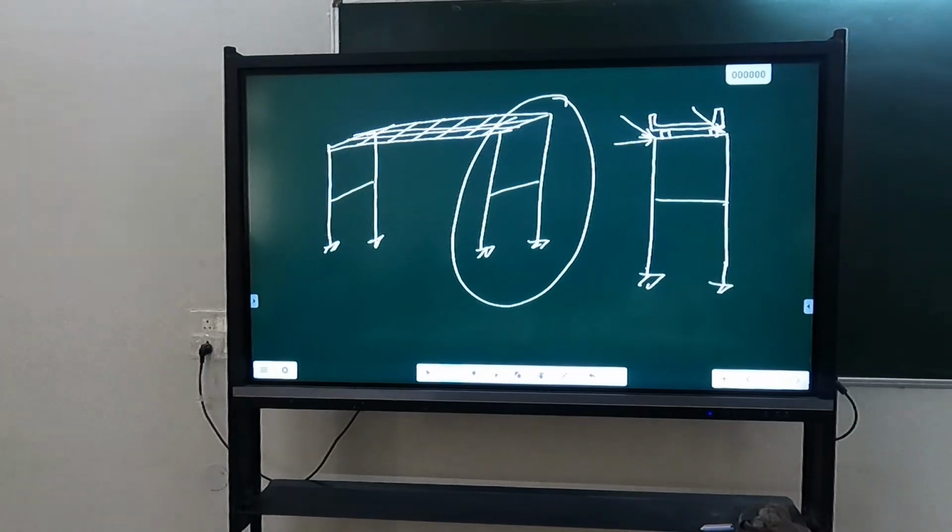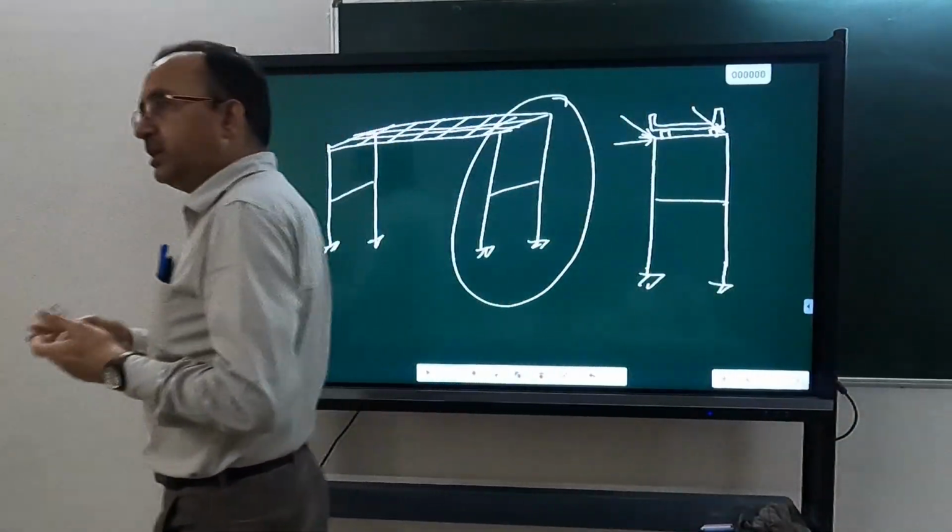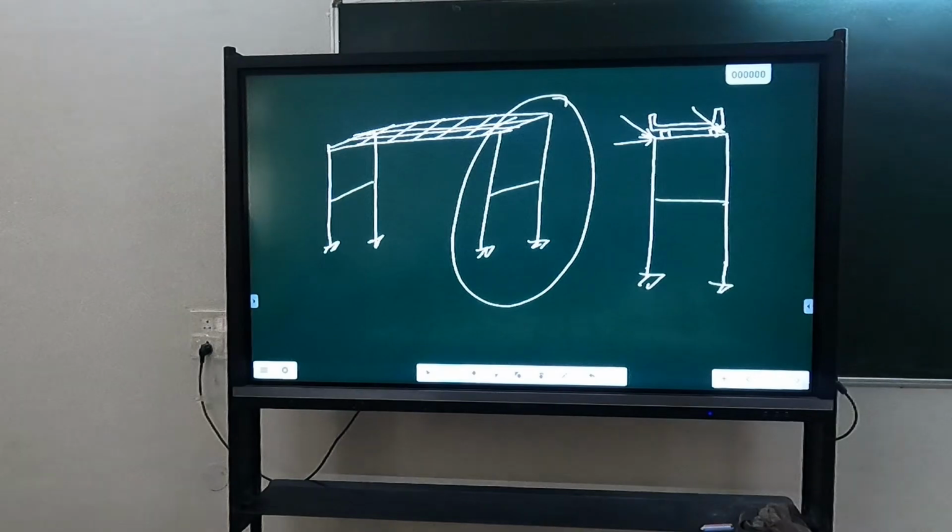Integral, so in the longitudinal direction you will get framing action because of the superstructure at column. In the transverse direction, multiple columns. So that will not be determinate neither in longitudinal nor in transverse direction. But most of our bridges will be determinate either in longitudinal or in transverse direction, or in both. Okay, simply supported circular pier or rectangular pier, single pier, that will be determinate in longitudinal as well as in transverse direction. Okay, so first of all, these are determinate.